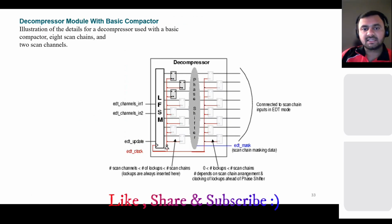As I told, on the decompressor side you have the channels, then the LFSR, which takes 2 inputs and generates 20 or many outputs. Then you have a phase shifter, which is nothing but XOR gates, and it is connected to the internal chains. This latch is required; you can see here we are using this lockup latch. Basically it is required to avoid data loss.